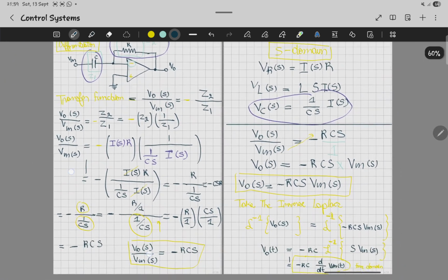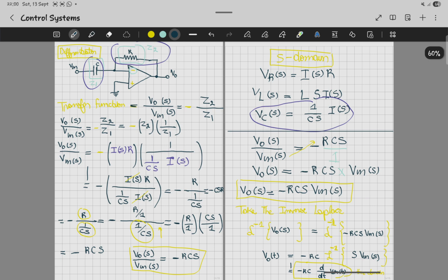And if you have to see the whole resolution, this is how I went about solving this question. Okay, so you just get a transfer function and then replace the S domain into the equation, and then you can solve for the transfer function and maybe V out at the end.